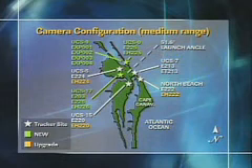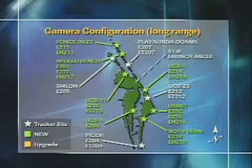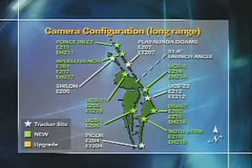And then the last tracking type we have is the long-range trackers, and that one's shown on the next slide. The purpose of those is coverage from acquisition of view. Some of those can pick them up right off the launch pad. Some of them have to wait a little bit to get it. But they go from as soon as they see it all the way through 15 seconds post SRB separation. Each one of those sites has a 35 millimeter film camera on it, a video camera.